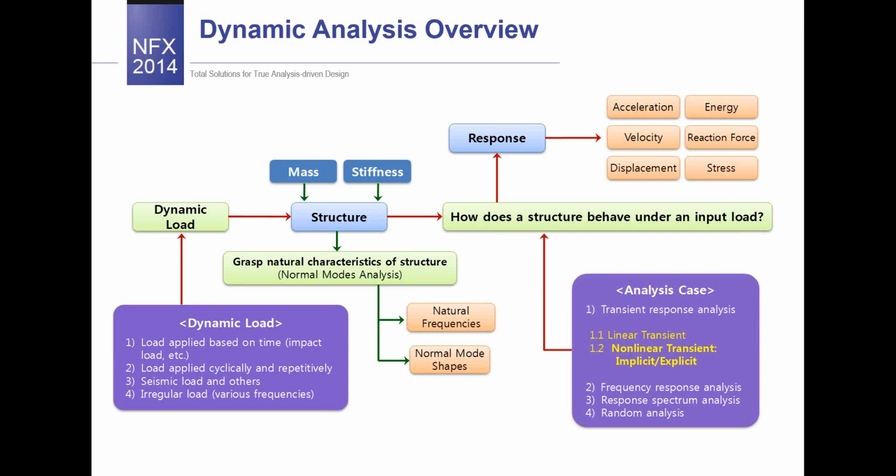So the main reason to perform any kind of dynamic analysis is when your structure is subjected to non-constant loading, which could be defined in time or, let's say, frequency domain. So there is a need to specify a dynamic load. Our structure should also include the information about the mass and the stiffness, and this is realized by material and property definition. So these two parameters should always be present in your structure or in your system.